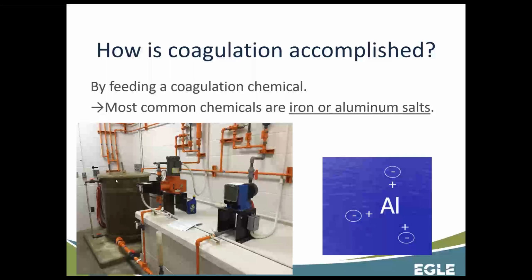And also it allows the operator, when they're making their rounds, to see that it's kind of graduated with some zip ties. Not sure what the system is at this plant, but maybe each one is how much coagulant you typically would feed in a shift or possibly a day. And the operators, when they're making their rounds, can take a look. And this is just sort of a gut check.